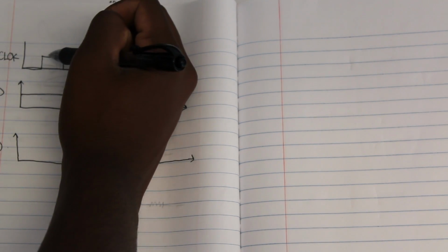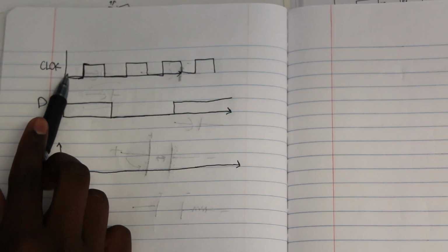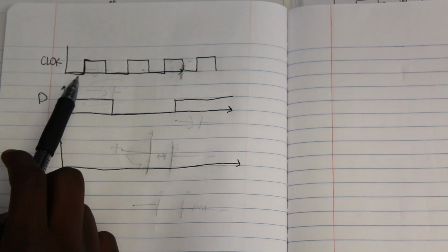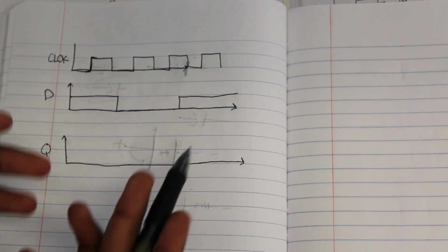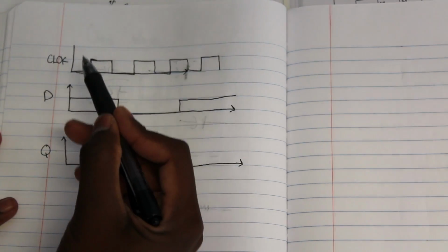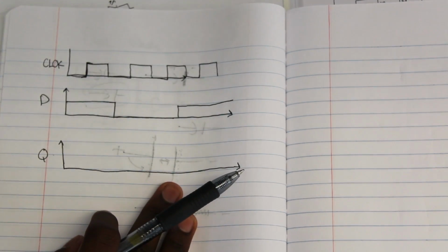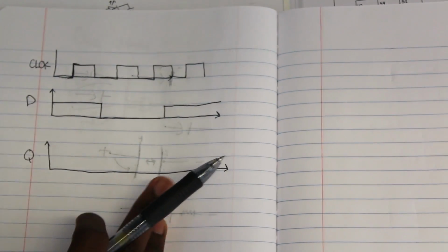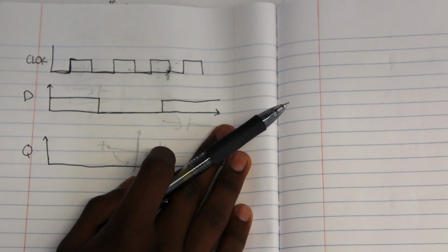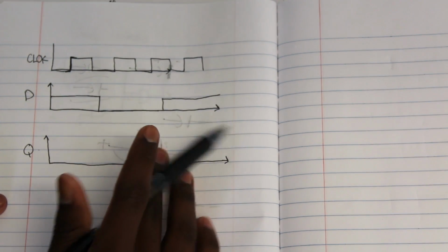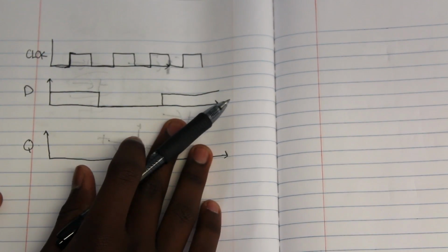So what you do is on this rise, my hand blocking it? No, okay. On this rise, this thing right here, you detect when the voltage changes from low to high. Not for how long is it high or how long is it low, rather you detect when it changes from low to high, and you do that with something called an edge detector. And I'll teach you guys how to make an edge detector later. It's the simplest circuit you guys have ever seen, but it's a good circuit, okay, and vital to the flip-flop.